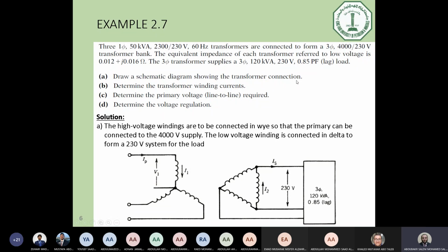Right. Let's start firstly from the required voltages. Now, you need the secondary of the single-phase one to be the same as the line-to-line voltage. What is the connection in which the phase and line voltages are equal? Which connection has this property? Delta. Delta connection. Right.